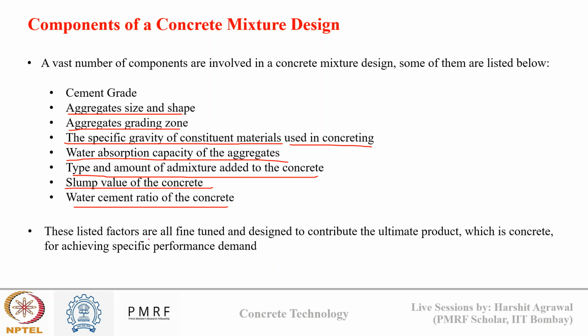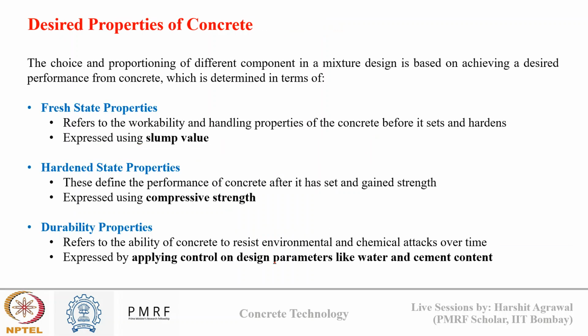Okay, and all these factors need to be fine tuned and designed to contribute to the ultimate product, which is concrete, for achieving a specific performance demand. Now, the choice and proportioning of these different components in the concrete mixture design is based on achieving a desired performance of concrete. And this desired performance can be determined in terms of different states. For the fresh state property, which refers to the workability and handling property of concrete before it sets or hardens,